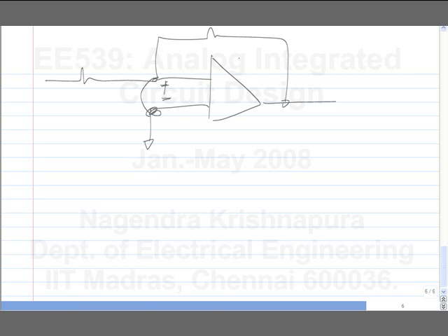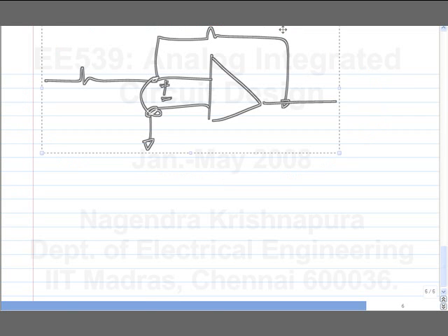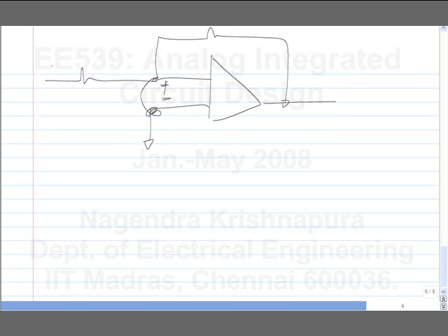I don't fully understand it, but it doesn't work. That's all I know. I mean, you can very easily see that it won't give you the right answer, right? If you short the inputs. The idea with this amplifier is the current in this resistor should flow through the other one. But if you short it, it will flow here.